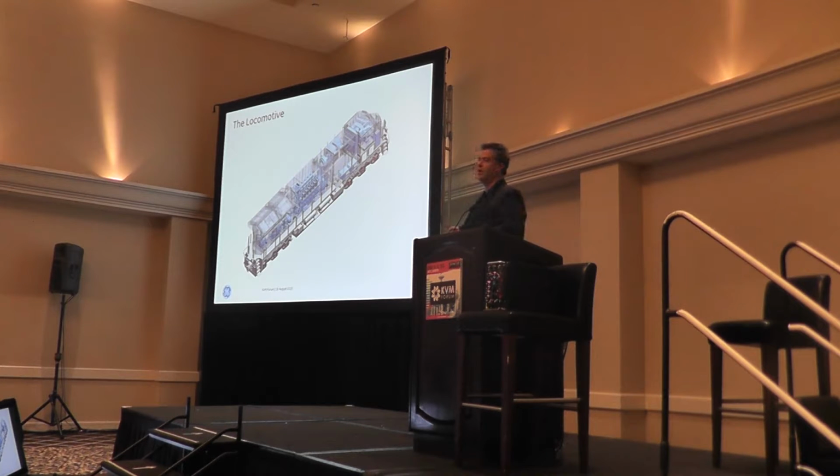With having a power plant on wheels, one of the things I always tell people is things like weight are not important. The more weight a locomotive has, actually, the more traction you'll have for the wheels on the rail. In fact, a lot of locomotives, when they're rebuilt or built with newer engines that might be lighter, they actually add weight. They'll add huge concrete blocks with steel in them, whatever, just to add weight.